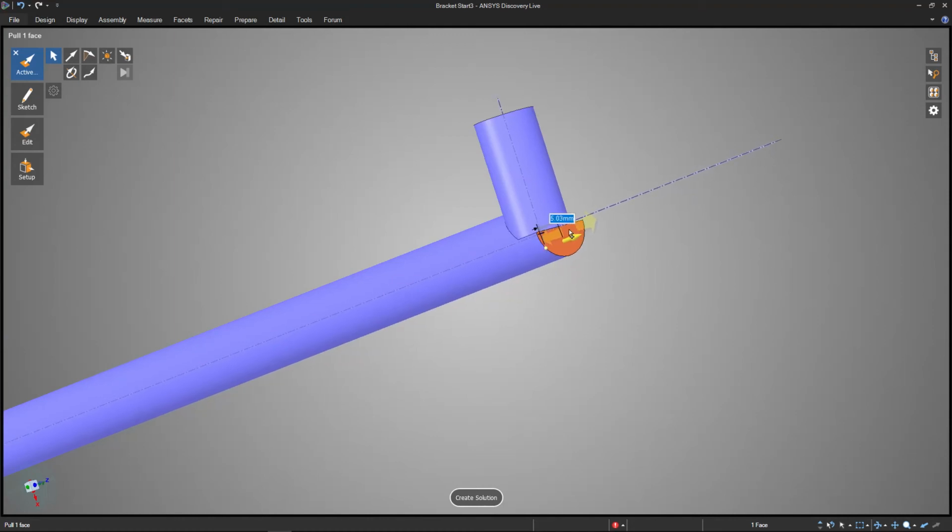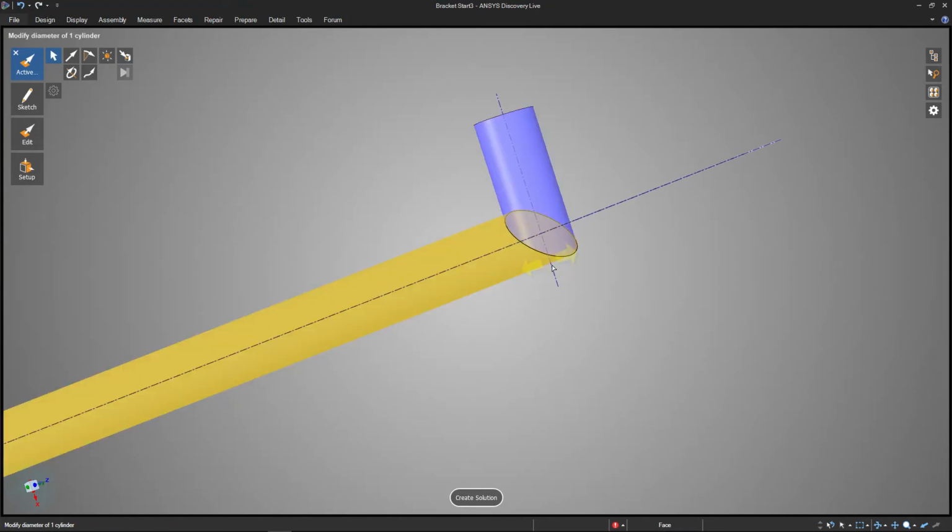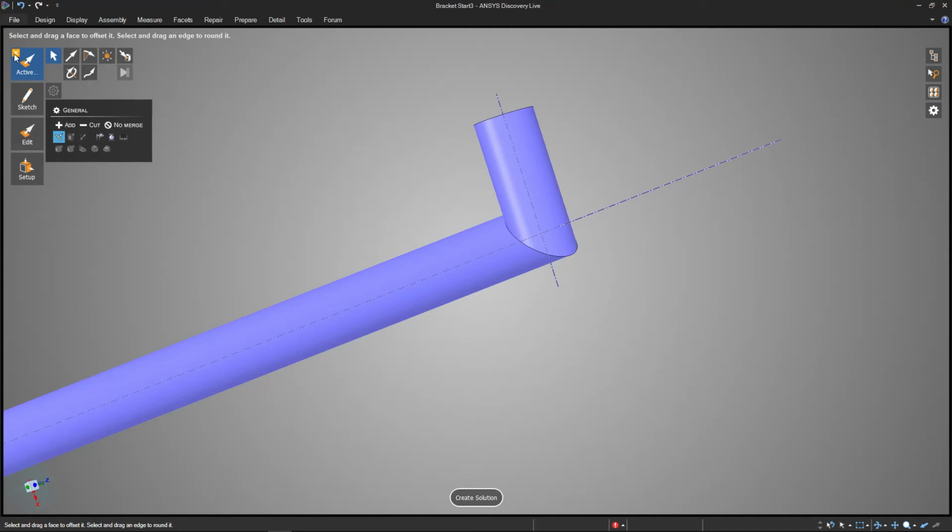It kind of knows that I want it to be cut out from that top shape, but it's a little hit or miss here. So we've got some extra tools in the Pull option here. If you click on it and you get the contextual menu that pops up, we can do the Pull Up To tool, and I'm just going to click on this face then. And so it pulls it right up to this intersecting cylinder there and makes a real nice looking finish.